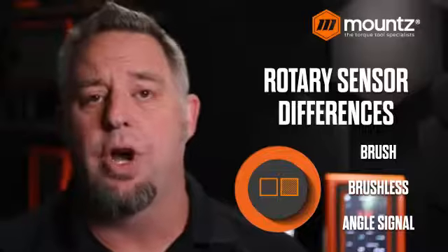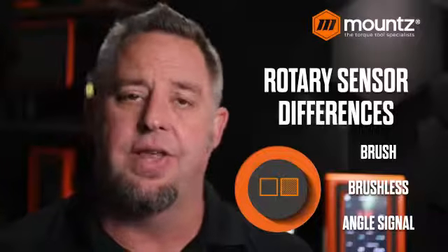You could also do a line test, where you would mark the part and the fastener, break that fastener loose in the loosening position, and then retighten that fastener to the line on the fastener and the part, and we can see what that value is. That would be representative of the actual torque that was delivered.